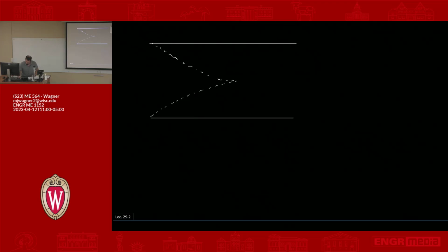Okay, so if I picked a position, let's say here, I want to draw what the velocity profile looks like. We have coming in, maybe to start, on this edge, with the leading edge, you have U infinity. So I'm going to draw this here. You're going to have a velocity profile at the wall that has the no slip condition, so the velocity is 0 there. And then as you go up, it starts to kind of taper off like this, right?